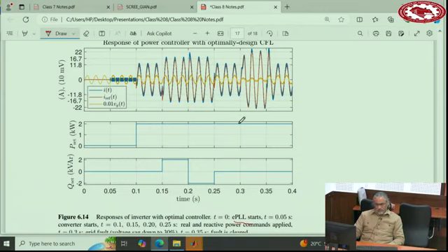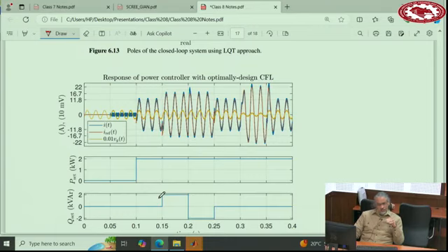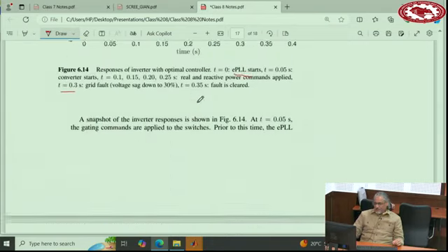The other thing we need to test is the current limiting. For the current limiting, we can apply a fault to the grid voltage. So a grid voltage fault, I think, happens here at 0.3. The voltage sagged down to 30%. So the voltage deeply goes down to 30%. So the current tends to increase 3 times, but the controller limits the current. There is a little overshoot at the peak, but it goes back. See? So at 22 it really limits that. Okay.